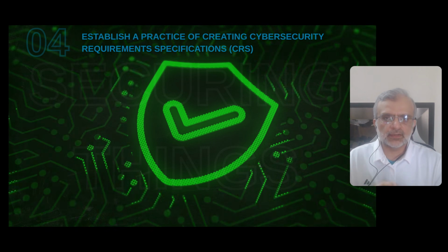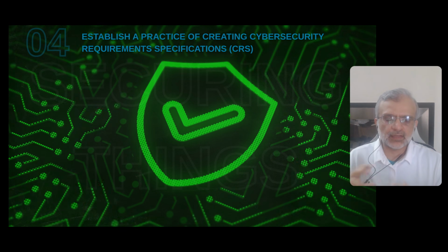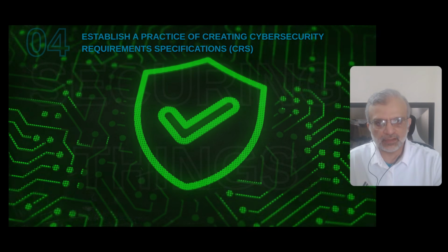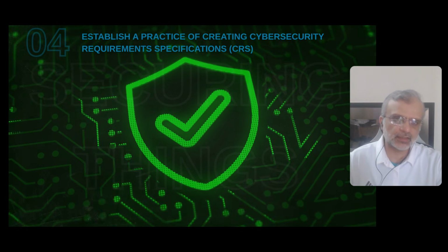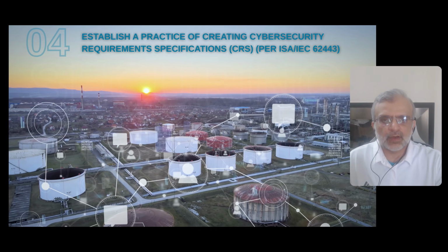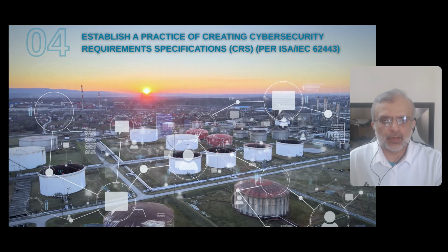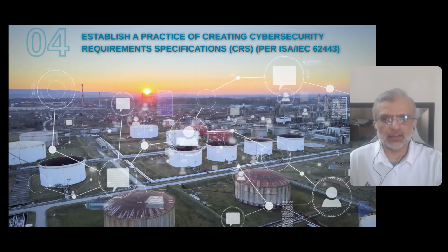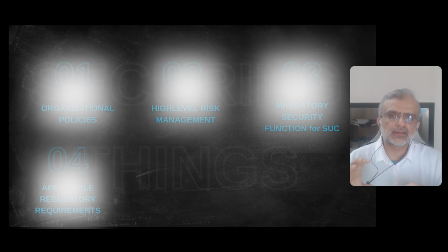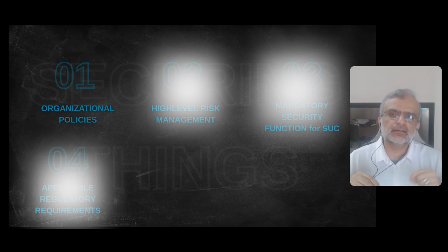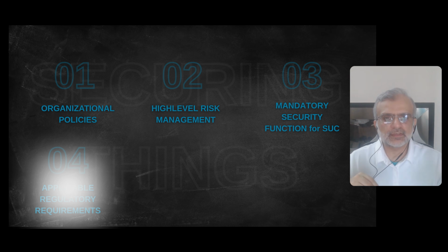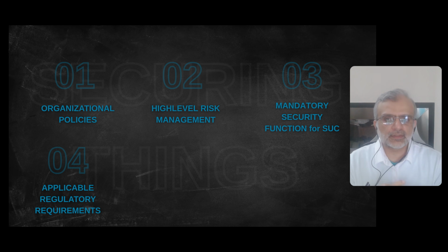Next, for the IT/OT environment, establish a practice of creating a cybersecurity requirement specification, or CRS, for all greenfield and/or brownfield operations and/or upgrades. A cybersecurity requirement specification per IEC/ISA 62443 standards includes the following elements. The requirement specifications are based on organizational policies and standards, the high-level risk assessment, mandatory security functions for the system under consideration or SUC, and any applicable regulatory requirements.